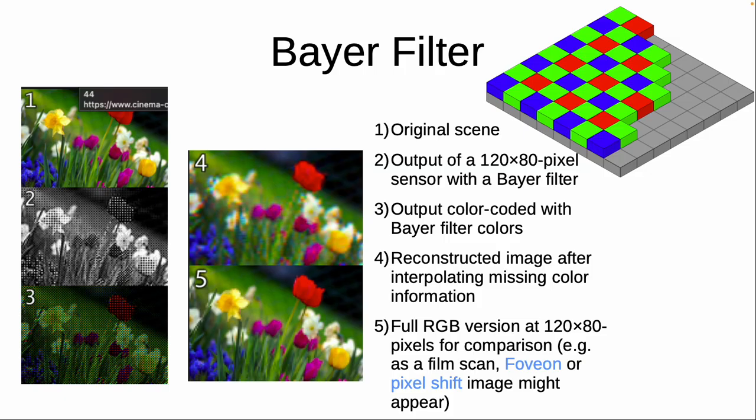Then they get a number of point data for each of the points, but the human wants to see RGB, so you want to see a red, a green, and a blue color all on the same pixel, and so they do debayering to convert that into RGB. Very well described on Wikipedia if you want to learn more. That, of course, increases the size of the data by a factor of 3.